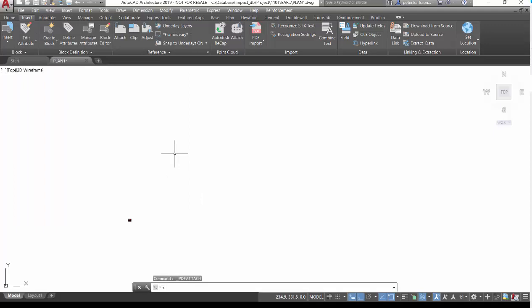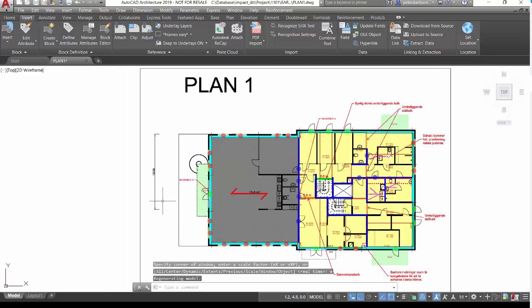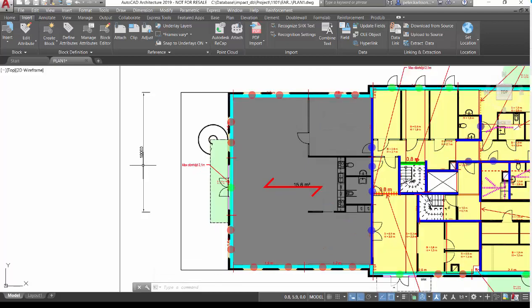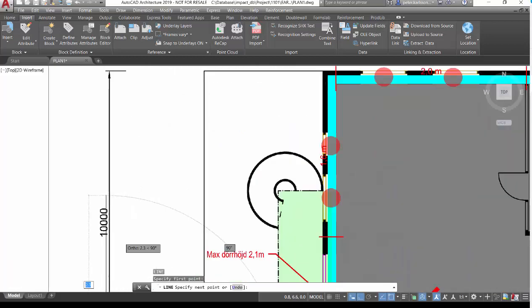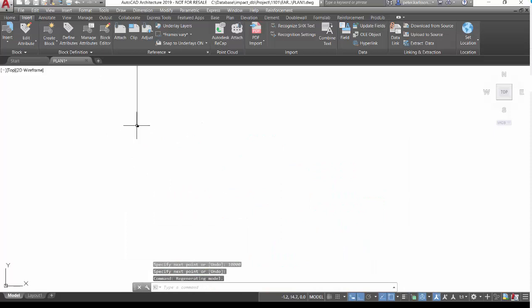So then I take zoom extends on it. And now I like to scale it up so it becomes the correct scale. And then it's very good that I have a measure that I can scale with. It could be this one, it could be something else. But of course it's good if it's a big one. So then I run align and I click from here and I say 10,000, which it stands there. So 10,000 in AutoCAD, like that.